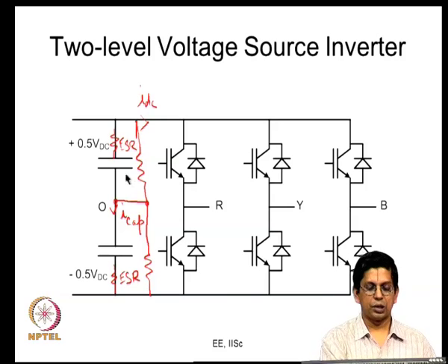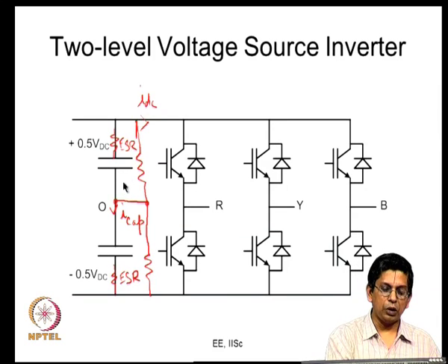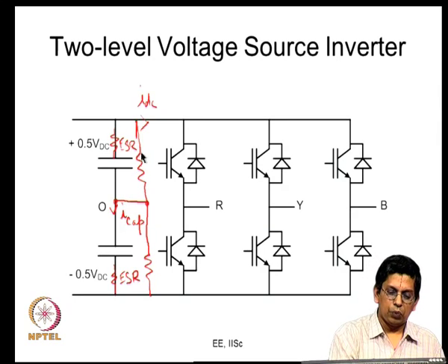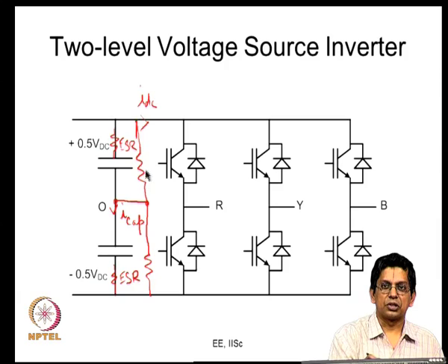Sometimes one capacitor has higher voltage and the other lesser, and this can eventually lead to stress on a particular capacitor and even damage to it. So, we would ensure such resistors, called bleeder resistors, which will make sure that there is a certain amount of power sharing.